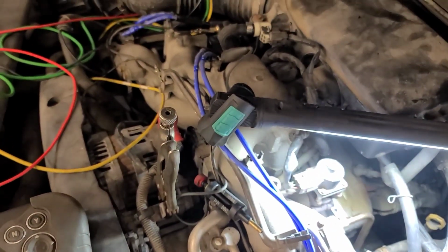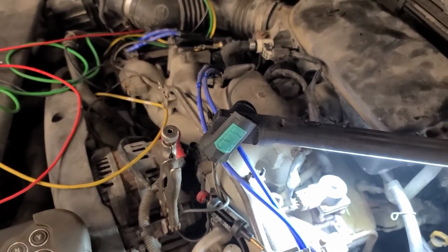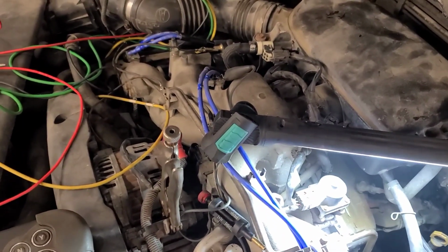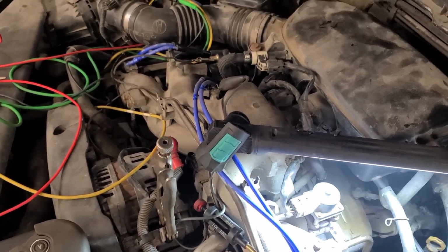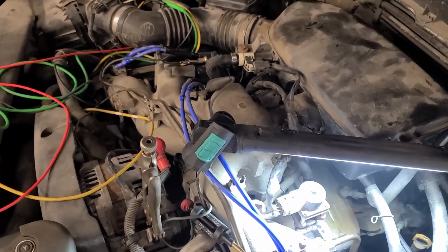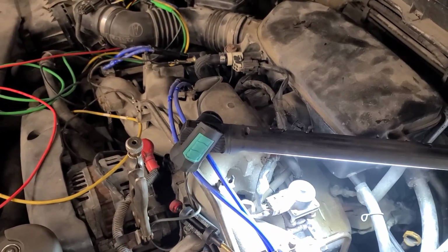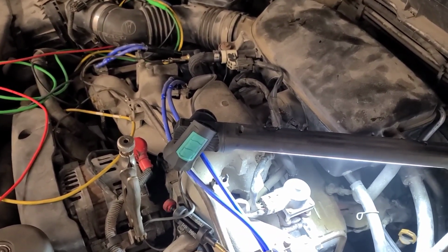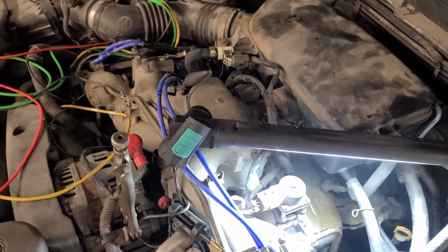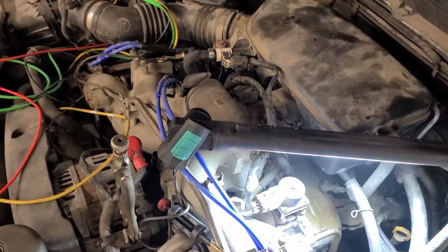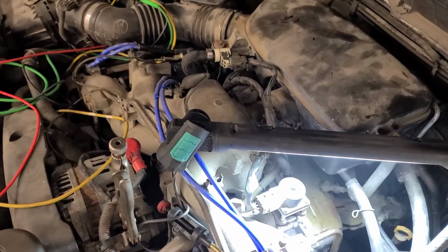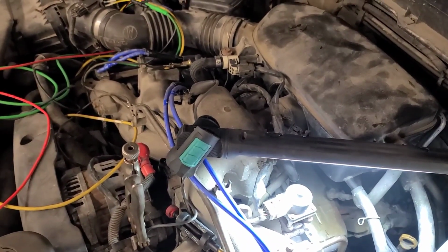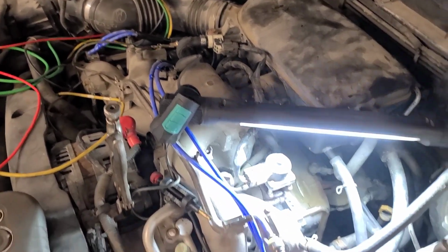I swapped the ignition coil with the original coil. The customer informed me that that coil was replaced back in June, but that was prior to putting the engine in, and it is an aftermarket coil. All indications are that it's a defective coil. I appear to have a trigger signal into it, power to it, but yet it's got no spark. But again, why wouldn't a warm coil, if that's the problem, fix it?